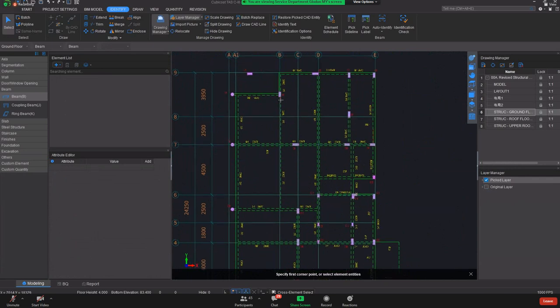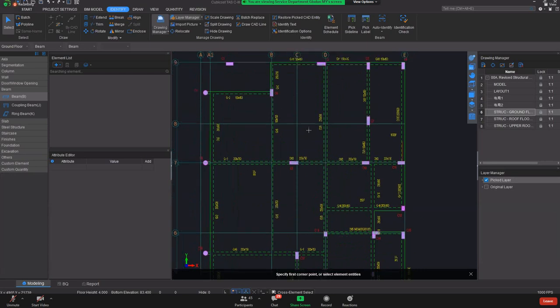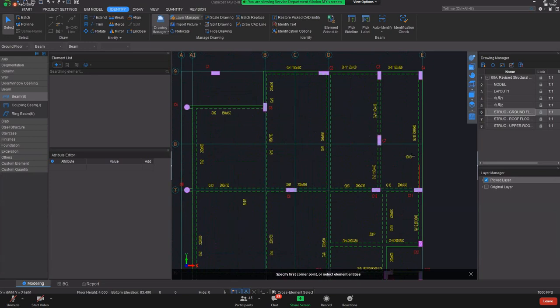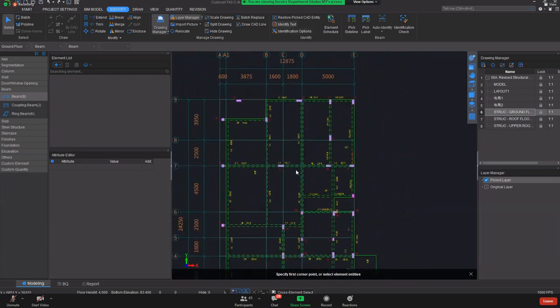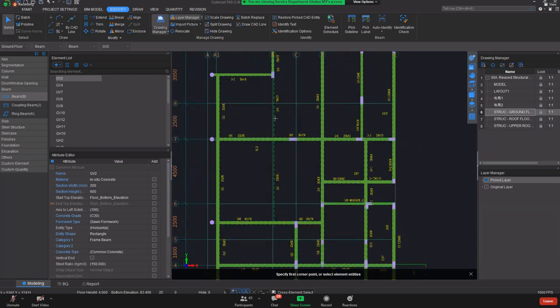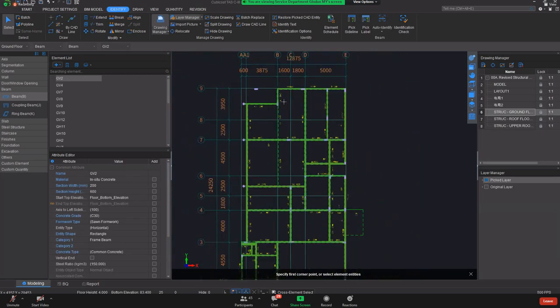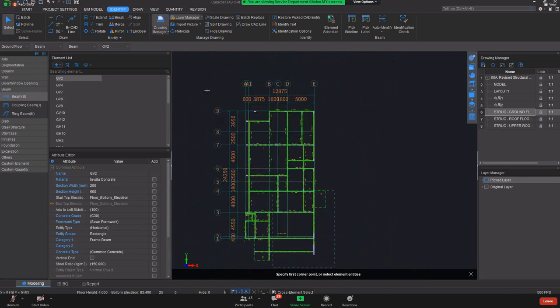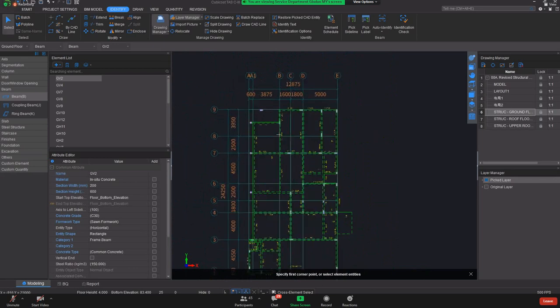If something happens wrongly, what you can do is delete all your beams. One moment. Currently you have this beam, right? I want to re-identify again. You can close this cross element select, and then you just left click and drag everything, the beam, and you just press delete. Then it will only delete your beam.